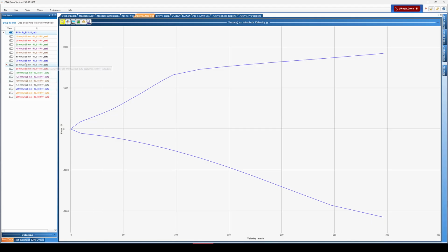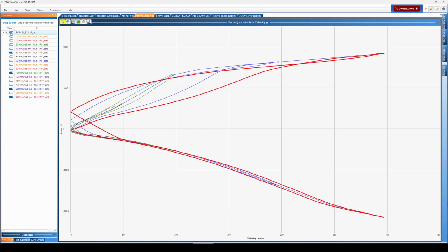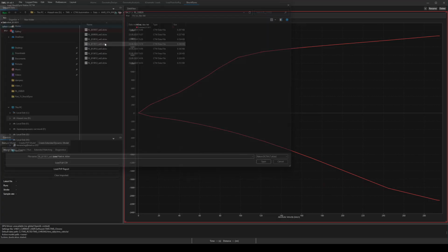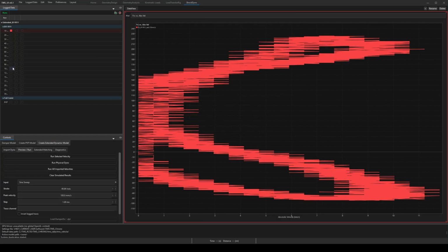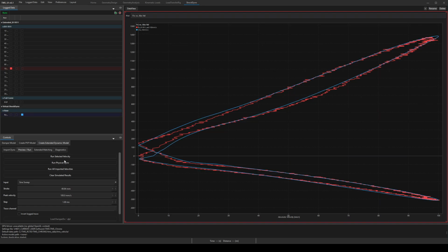The next branch is the extended dynamic model. This one is for engineers who want to go a bit deeper. It is well known that clean peak velocity plot curves are not exactly what the damper is doing in reality. Actual damper force does not simply follow the ideal PVP curve. This branch is designed to import raw dyno data and reverse engineer the measured behavior, including hysteresis effects. Here, a one-dimensional solver is used to produce a damper response that is closer to the real measured response.